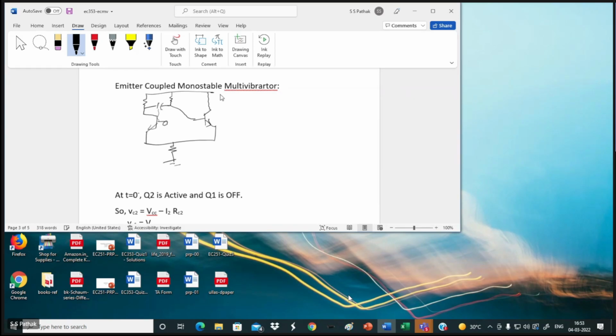Here is my VCC. So VBB is not coming in this case. VBB was grounded in the previous case. So single power supply I am working. This is the way I call this my R and call this my C. This is my RC1 and this is my RC2. Why am I putting this? Because T1 and T2 you might be controlling in a different manner. Okay. So this is my RC2 and RC1.